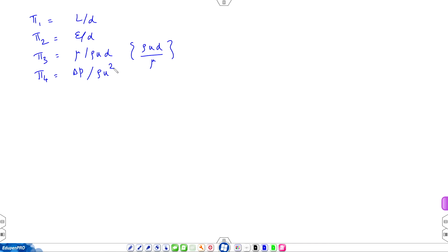Though epsilon will have either, I think some table was given to you. You remember the tutorial problem sheet, epsilon has been given to you. I think that because it is an American book, it also has feet, inches, meters, millimeters, microns. So, units of length. And what is epsilon? So, epsilon is an average height of the roughness element. So, this roughness is distributed over the surface and its typical value, not maximum or minimum, but something like a representative value.